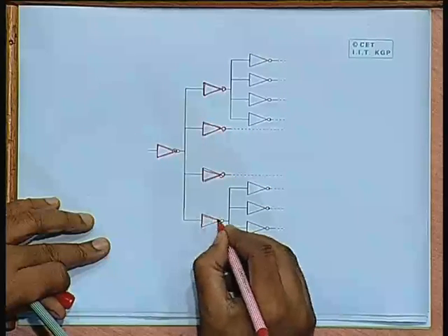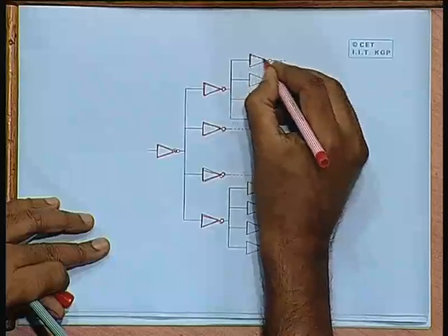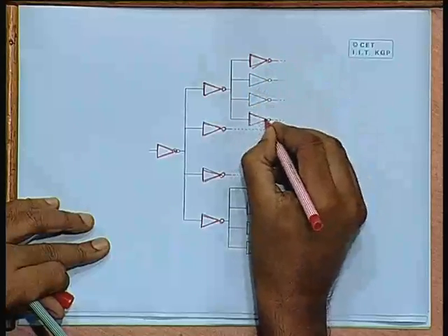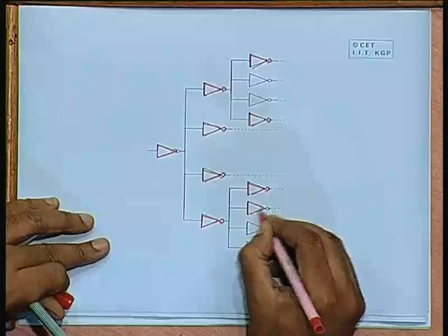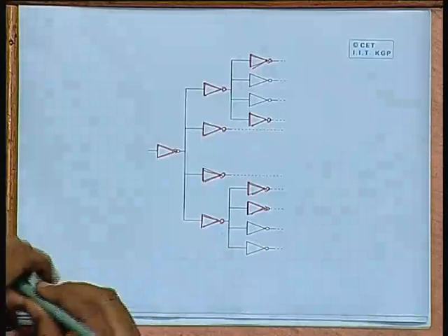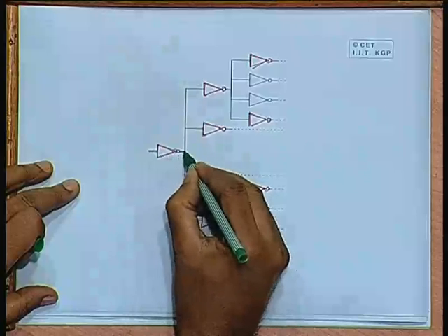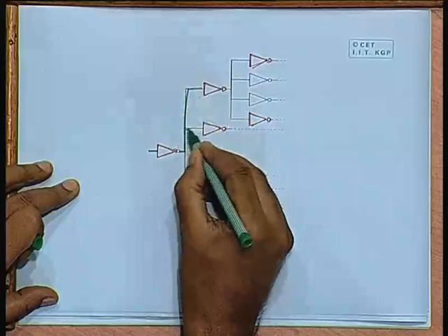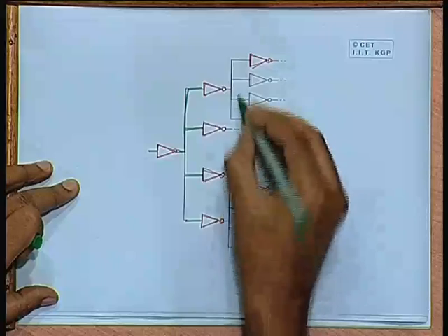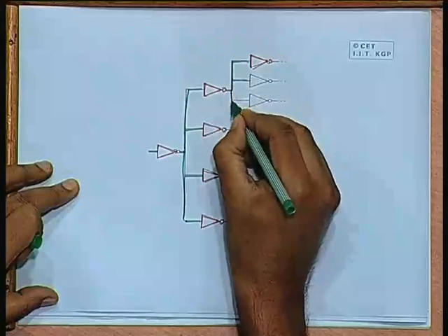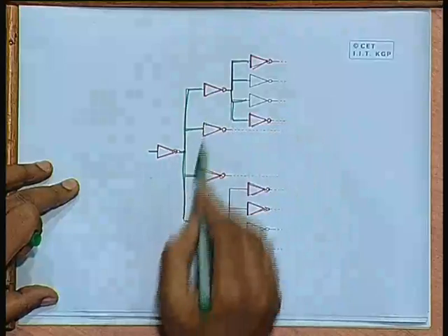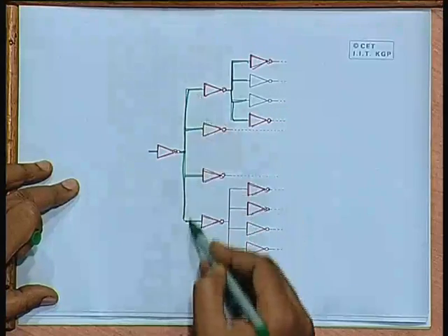These are all distributed on the different segments of the tree and so on, and from the clock source you distribute them like this. Now, the buffers are called identical because, for example, in this example I have shown the fan out of each of the buffers is 4 in the first stage as well as in the second stage, as well as it will be in the third stage. So, the final buffer also will be driving 4 clock pins.